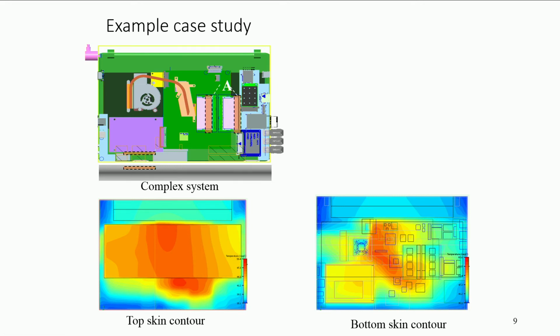So, there was one case, maybe I can say that after 7 years, not a problem, back in 2010 I was trying to design some, and it was the delta T that was killing the design. Both temperatures by themselves were within limits, but one of the palm rests was much cooler than the limit. So, what I did was I took a simple metal plate and connected the two. I heated up something which was already overcooled. I was supposed to be a thermal designer cooling down stuff, actually I ended up heating because it was already cooled, and when I connected the two it was okay, all right.